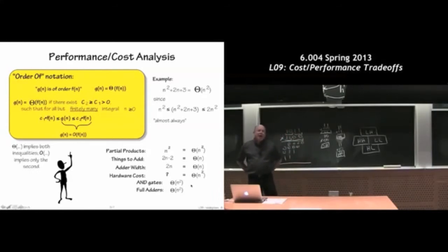So this is a quick overview of how many pieces of hardware we need to build a multiplier in this case. And you might say, well, look, I have the AND gates forming the partial products 1 bit at a time, and I have n squared of those, and then I have all these full adders. I need a lot of each individual building block here for adding together bits in a column. I'll ultimately need about n squared of those adders.